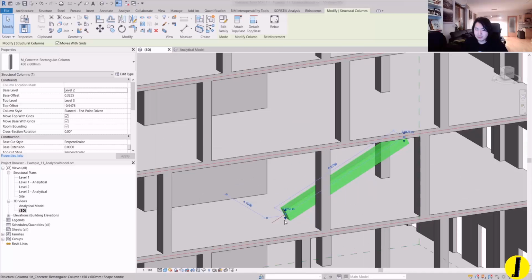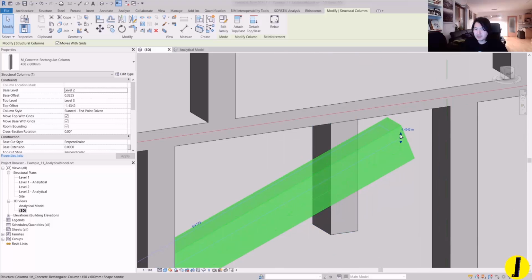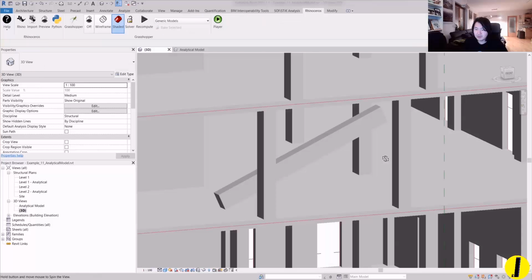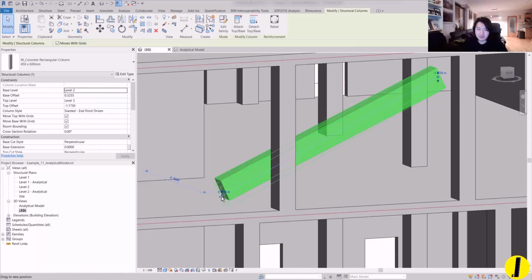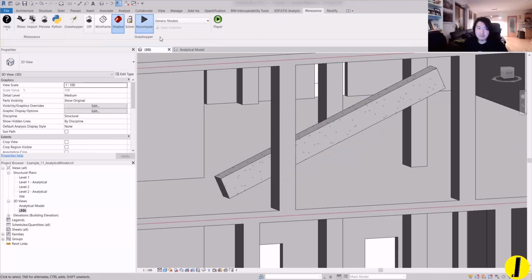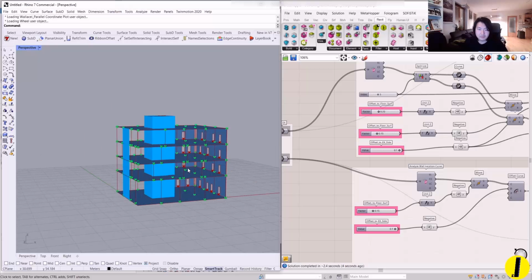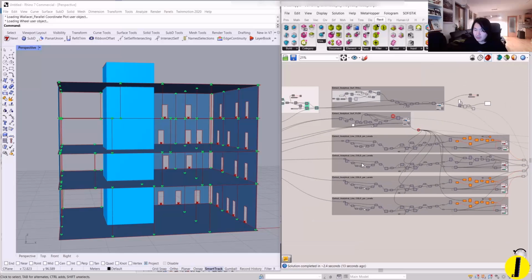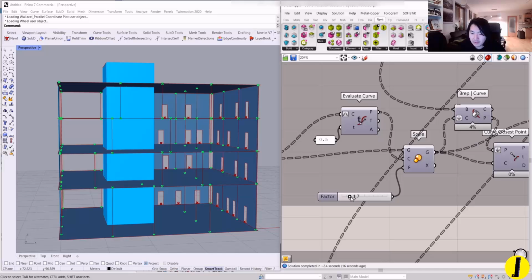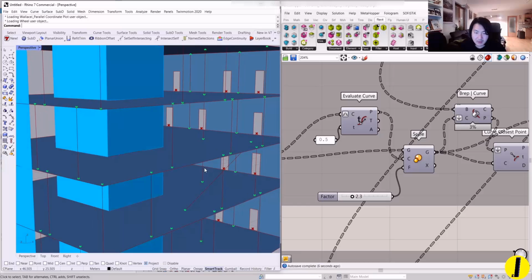further, or maybe you can change the slope angle. If it's out of the tolerance, then we have to increase the tolerance from the script. But when it's within the tolerance, then when I recompute, the elongated line should match. Okay, so maybe it's still out of the tolerance. Yeah, recompute. Let me go to Grasshopper and Rhino. Oh, okay, so the slanted one I can check here, in the column parameters. When I increase this tolerance, they match the slab.